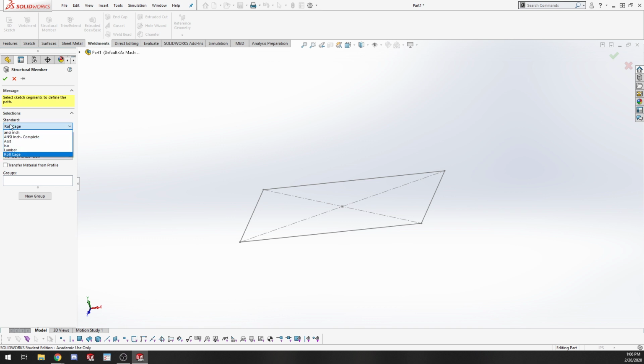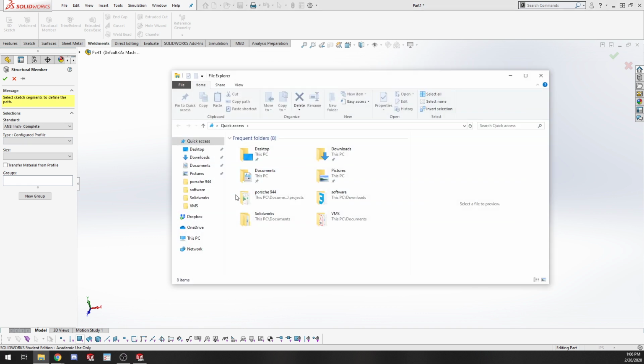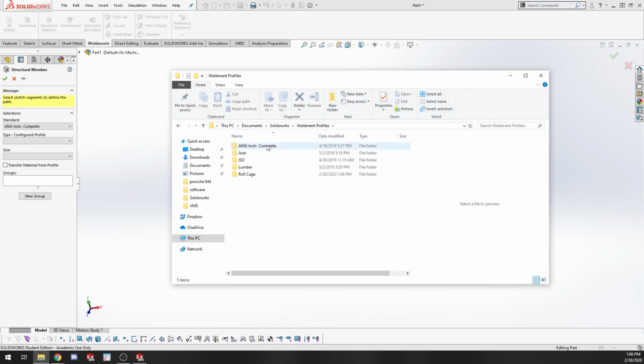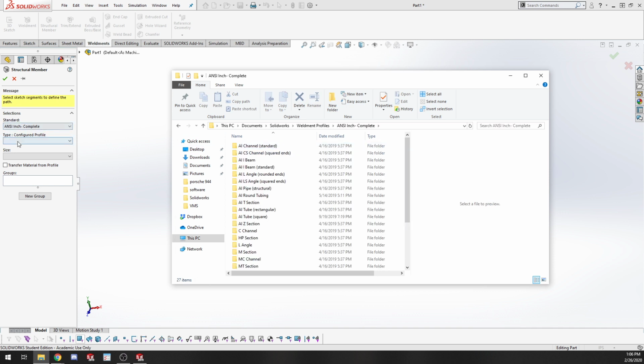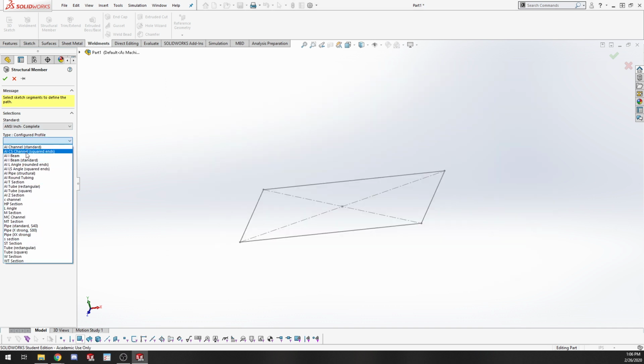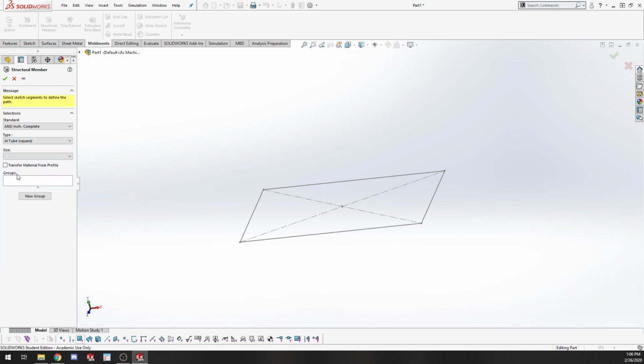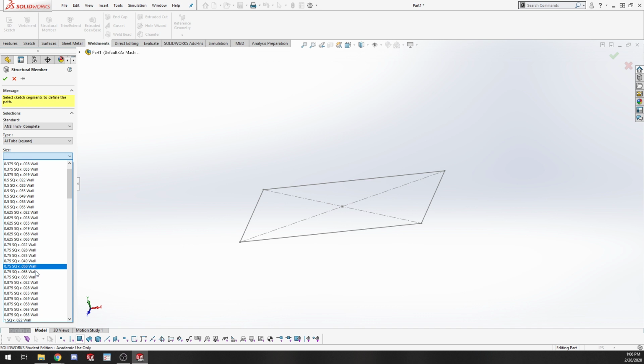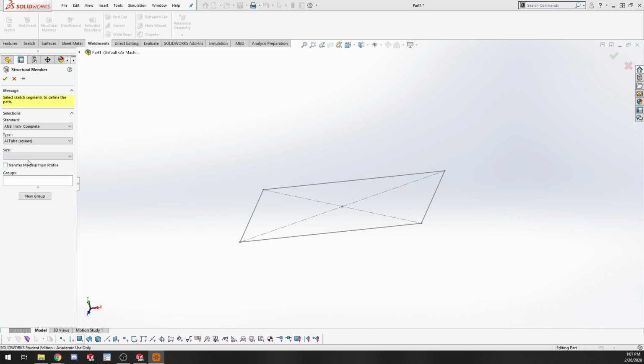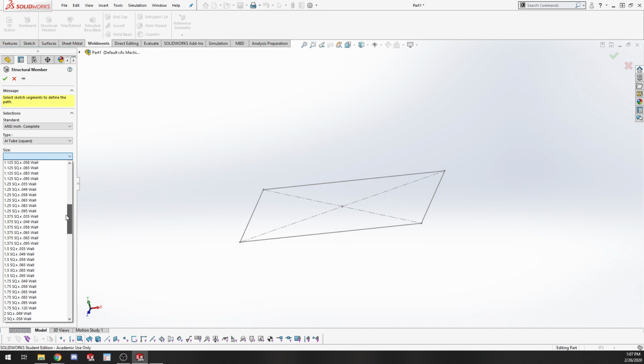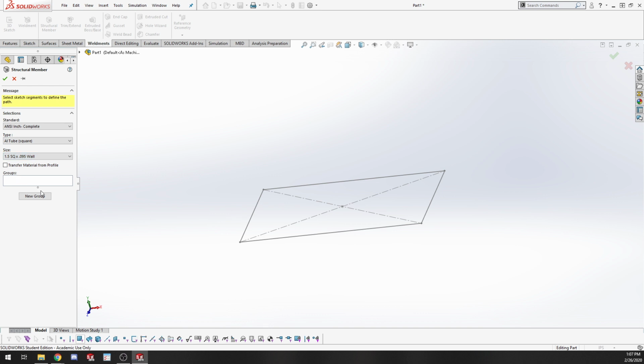So in the standard folder, if you remember, that's that first folder name. Let me pop that back open, actually. SolidWorks Weldment Profiles. This is my standard name up here, and then my type down here. Let's see, we need square tube. Fancy inch tube, square. And then we'll drop down, I think we said 1.5" tube is what we want to use. So we'll go down here, 1.5", do 0.95 wall. Cool. All right, and now what we do is we add in groups.